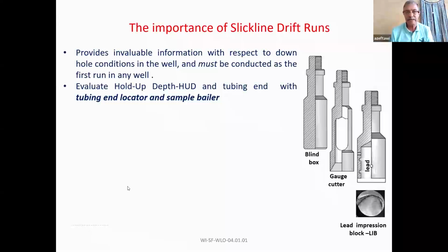Could you please explain the bullheading from the last lecture, as the downloaded video on YouTube was not complete? Although this is not part of the course, but sure. Bullheading is one technique of killing the well, where you have to do what we call an injectivity test. You have to be sure that bullheading is a squeeze. You squeeze the kill fluid into the formation. But to do that, you have to do an injectivity test for the formation, because some formations are like a check valve. You can produce from, but you cannot inject into.